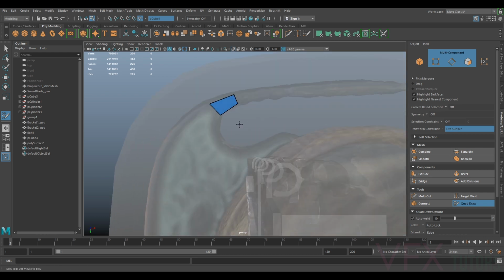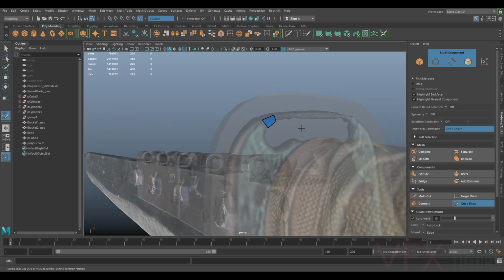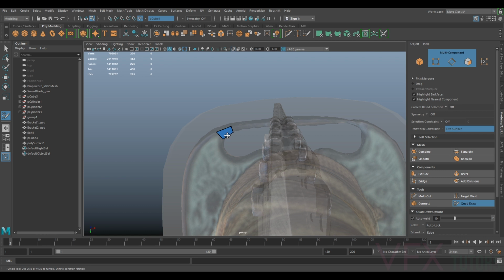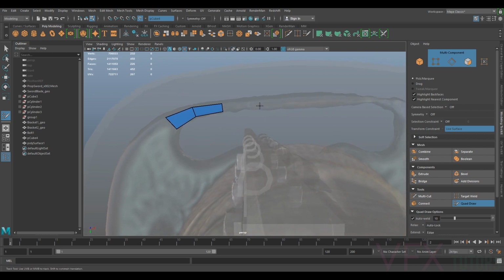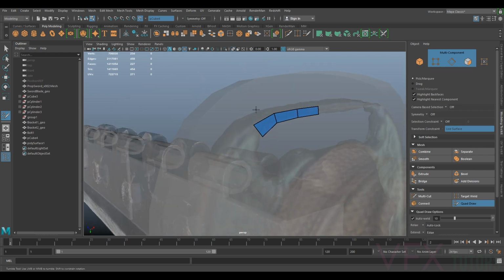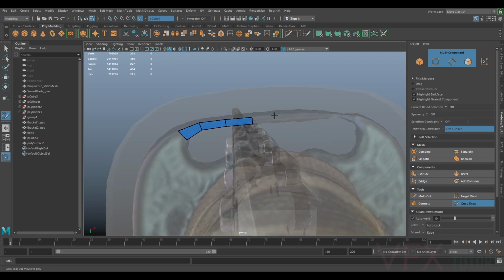You can see that I'm tracing the actual mesh, but I'm drawing onto my geometry. I'm not drawing onto this mesh. I'm drawing onto that rough mesh that I've literally just made. The reason I've done this is because if I was trying to quad draw onto this mesh now, it would be trying to wrap around this edge, snapping onto bits there, and it would be a bit nasty.